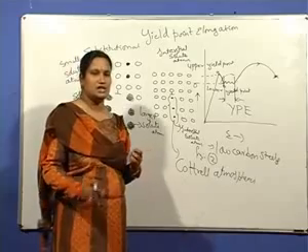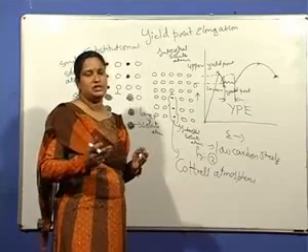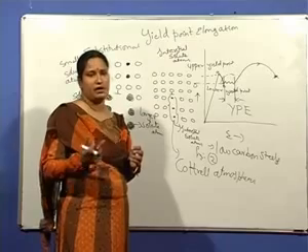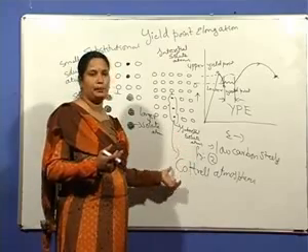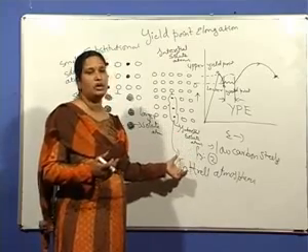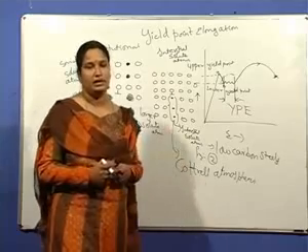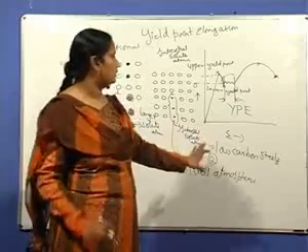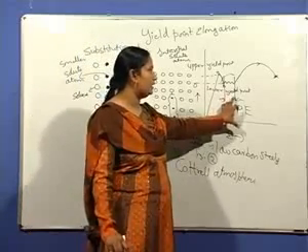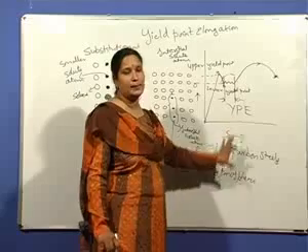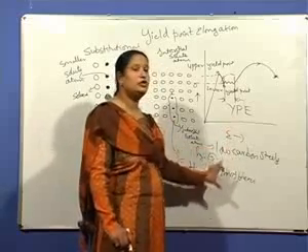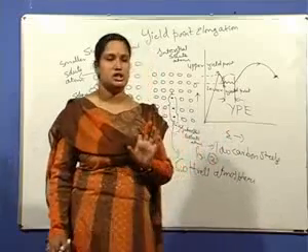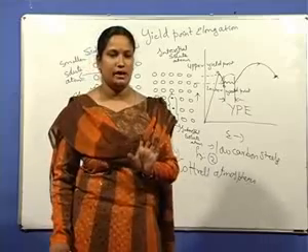The reason is, at such high temperatures, thermal vibrations are more intense. The mobility of atoms is more. So this effect does not exist above 400 degrees centigrade. The reason for the formation of this yield point elongation in the low carbon steels is mainly due to the presence of interstitial elements like carbon and nitrogen.